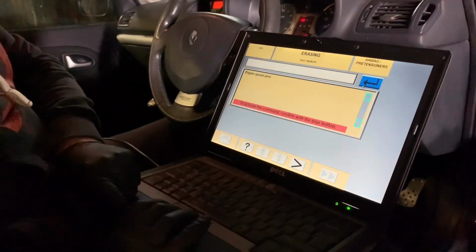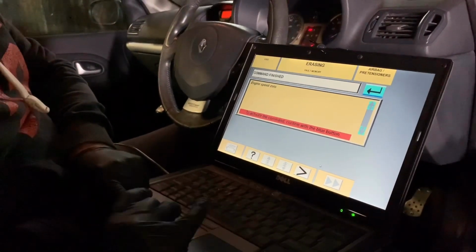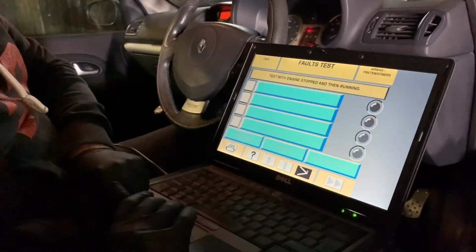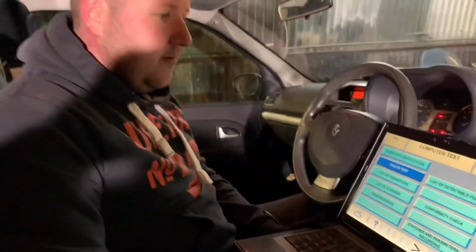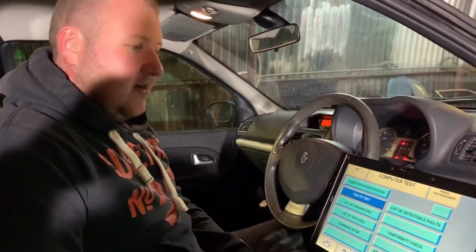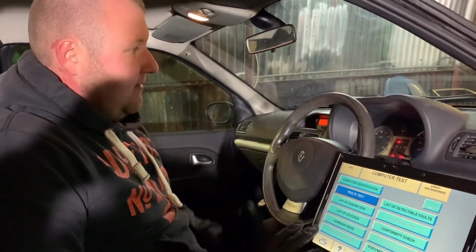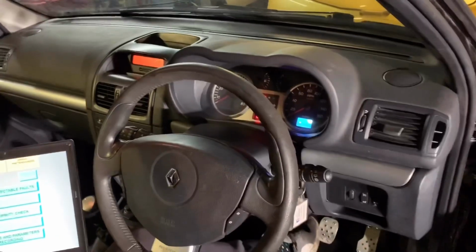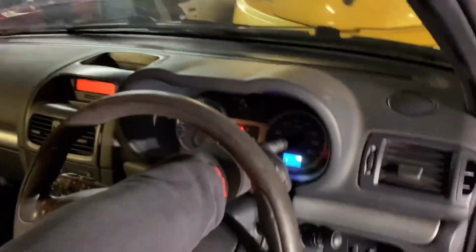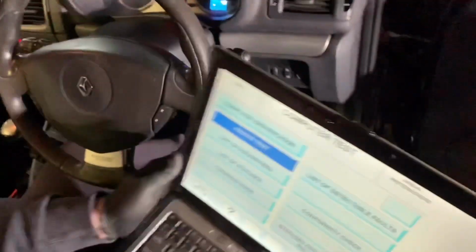Alt memory. Okay, that's gone. Now this is one of my own vehicles, so I haven't got a problem removing that component, but really it shouldn't be used if it's going to be a road vehicle. If you'd like to look at the dash, you'll notice all of the airbag lights are out. In the corner there, that's where you would normally find it. No airbag lights. But should it be a road vehicle, you would need to replace that component or repair it.